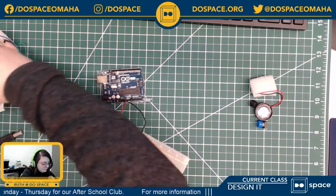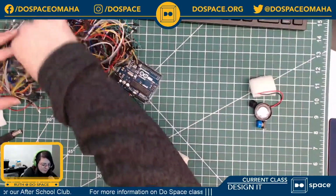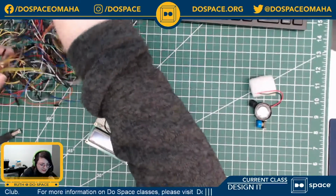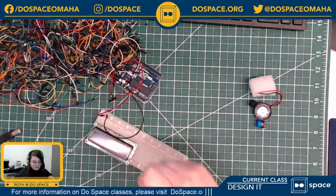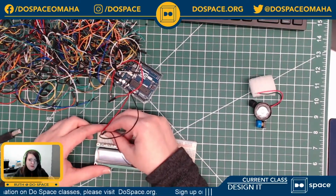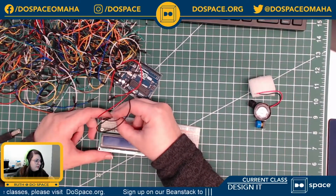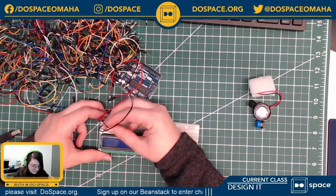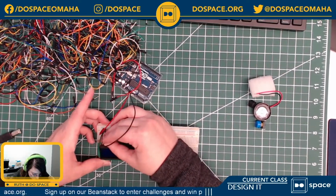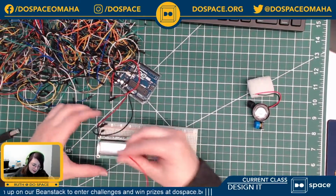I'm gonna pull out all these cords here. I try to stay color coordinated, but there are some times where I just don't have the cords to do it. There we go. So I'm gonna grab ground right here. Usually I want to connect ground first to be safe. And then I'm going to the first pin right here. Looking for a red cord, so I'm adding power now.